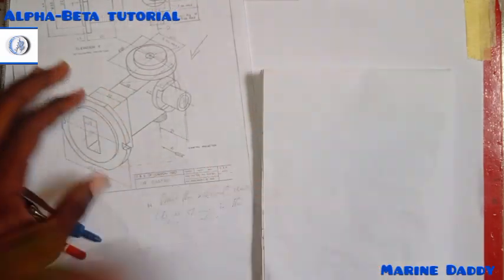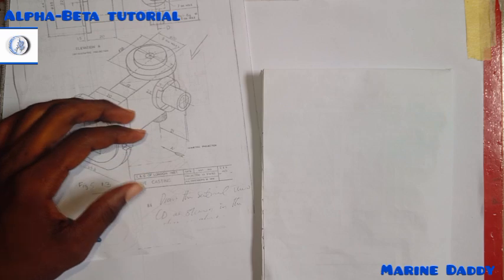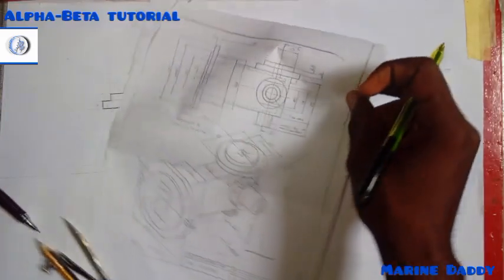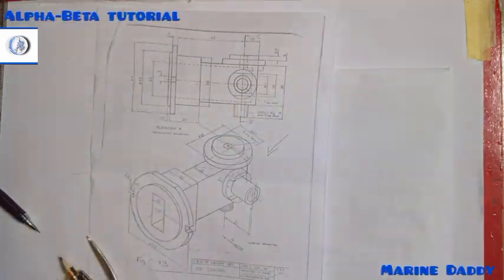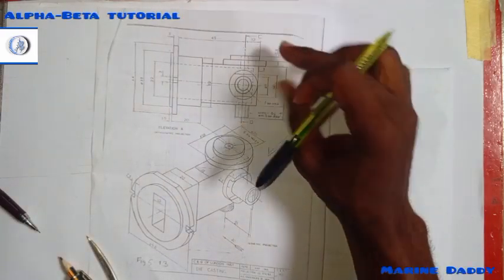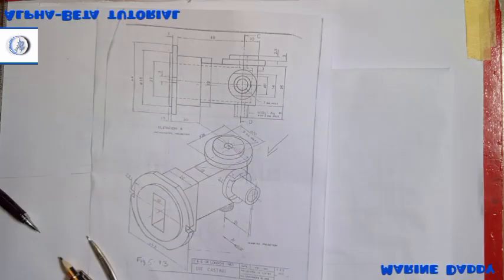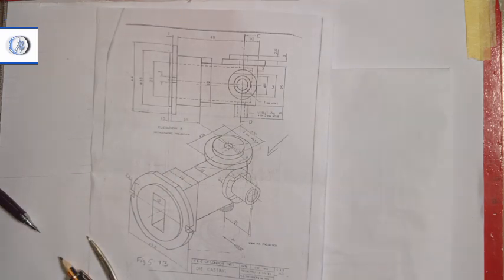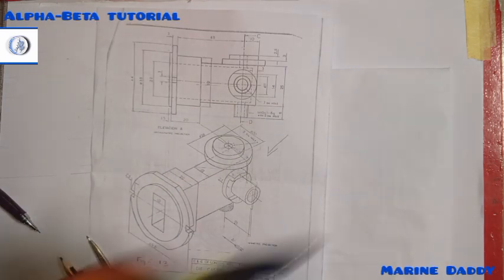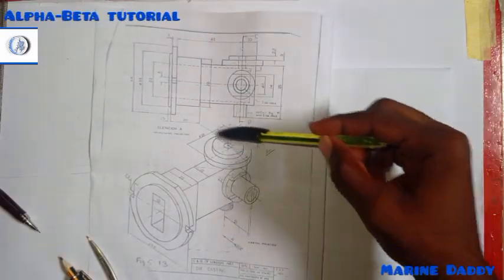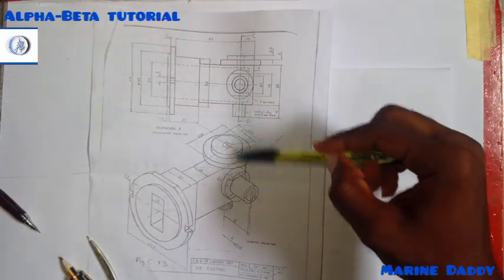So this one is a machine drawing question, and here you were asked to section the diagram from the cutting plane CD. So as usual, you locate where your CD is. From this side, I can see my CD at this side. So please, you need to observe where your CD is located. Then the cutting plane, how the cutting plane went through. Understand? So right here, the thing is cutting the back of the structure. That's at this side. It's cutting it downwards.